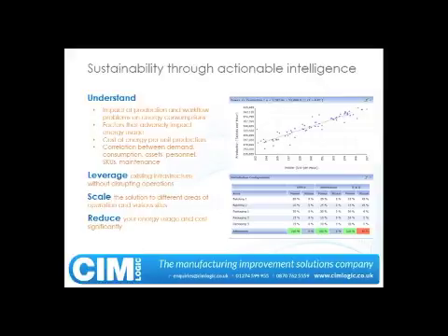And if we look at the chart over on the right-hand side, we've got a quick scatter chart and a trend line for our power consumption, kilowatt per hour, versus our production. It might be per ton, or in this case, it's tablets per hour. We can use that kind of historical data to set ourselves a benchmark. So if I know, for example, that tomorrow I'm expecting to produce around 300,000 units, I would be expecting to consume somewhere between 205 and 217 kilowatts per hour. And we can set that as a benchmark.